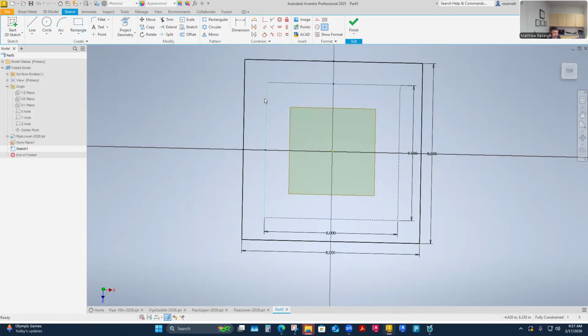But what this has, these lines have endpoints right here. These can work for the hole command. The hole command just needs a point placed, but when you have lines that intersect at a point, you don't need to place another point on top of this. These will function just fine. And I think some of you have already been using that, and that's great. If you can use this geometry to use your hole command on the actual 3D model tab when you come out of the sketch, you could also choose to, now that you have these easy, plop the centers of circles here too, and have those holes incorporated into the sketch.